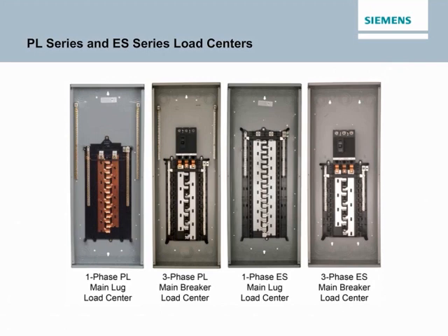The PL series load centers offer the following features. They are convertible from main breaker to main lug and vice versa. They're invertible for bottom feed applications. Insta-wire neutrals and grounds. Ground bus bars are included. Copper bus bars. Dual neutrals on all configurations. Carton packaging with trims packaged separately, as well as a lifetime warranty.